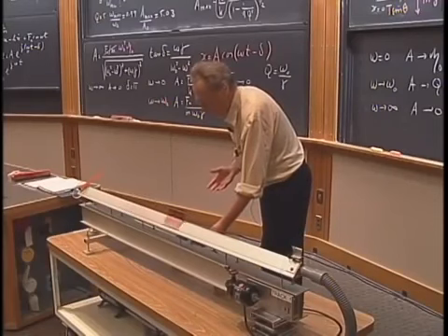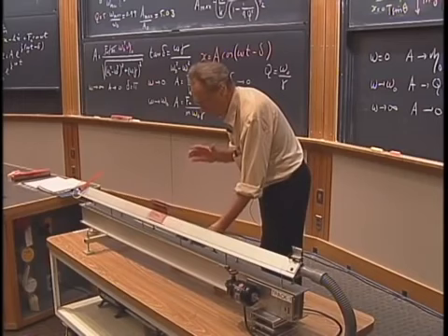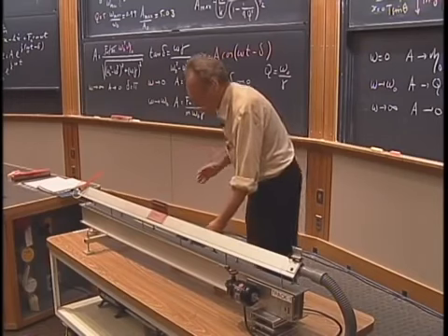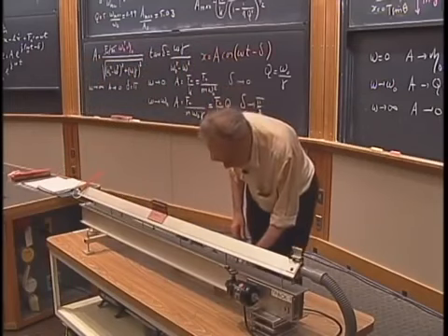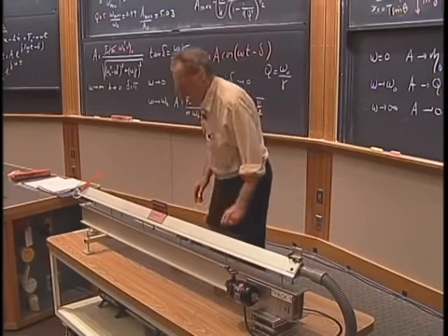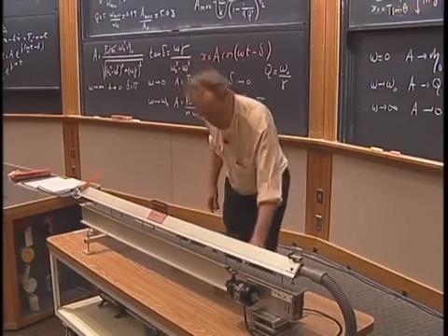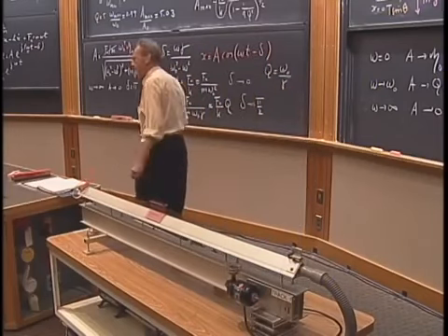Now I will oscillate it over resonance. First, the system must calm down. And now I will change the frequency above resonance so that you will see the phenomenon that I discussed earlier, that the amplitude is very small. Again, we have to wait a little, look how fast it's going, and that then will go 180 degrees out of phase.